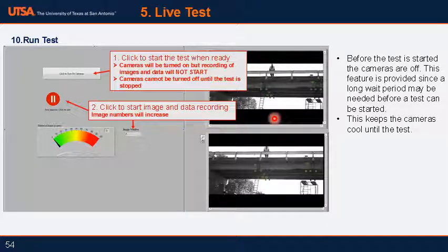If you've picked your targets well, with good contrast, with a match score that's above 900, that should not really happen. But sometimes things happen, like a wire goes in front of the target, or maybe the wind blows it, it comes in and then goes back out. So you may lose targets intermittently this way. And this is a good way to check. When you're looking at these square colors, you'll know whether your targets are being tracked or not.